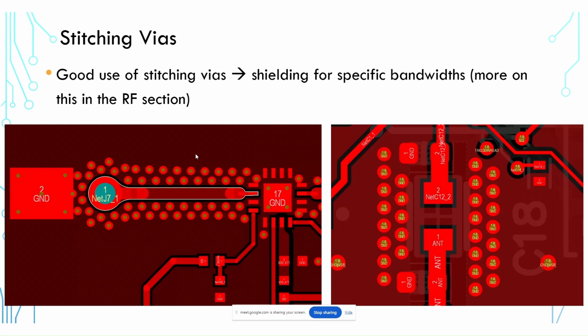So this is another very important point here, is that stitching vias help, but they are not the magic bullet against noise being coupled into this interconnect. Really, the best tool that you have at your disposal is using ground planes and then placing the components and circuits such that you don't have strong coupling between these different elements into this interconnect.